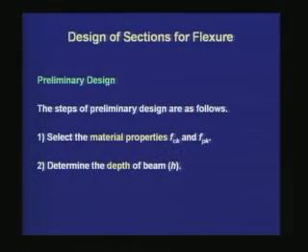Today we shall cover only the preliminary design, and in our next class we shall move on to the final design. For the preliminary design, the steps are as follows. Select the material properties fck and fpk, which are the characteristic values for the concrete and the prestressing steel. Determine the depth of a beam, which is represented as h.